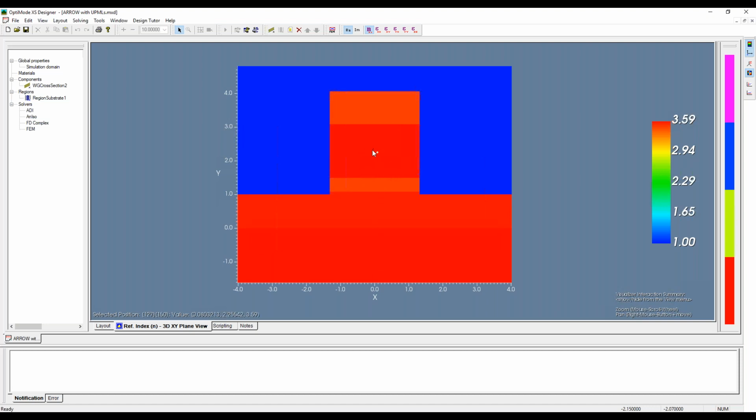In the middle here, the core is 3.59, and the slightly off red color here, a little bit oranger, is 3.452. And there's also another layer down here that you probably can't even pick up on this webcast because the color is so close, but it's also slightly off. It's 3.555. And then down here, it's the same refractive index as the core, which is why this mode will want to leak out into the substrate, even though there's some type of barrier between it and the substrate.